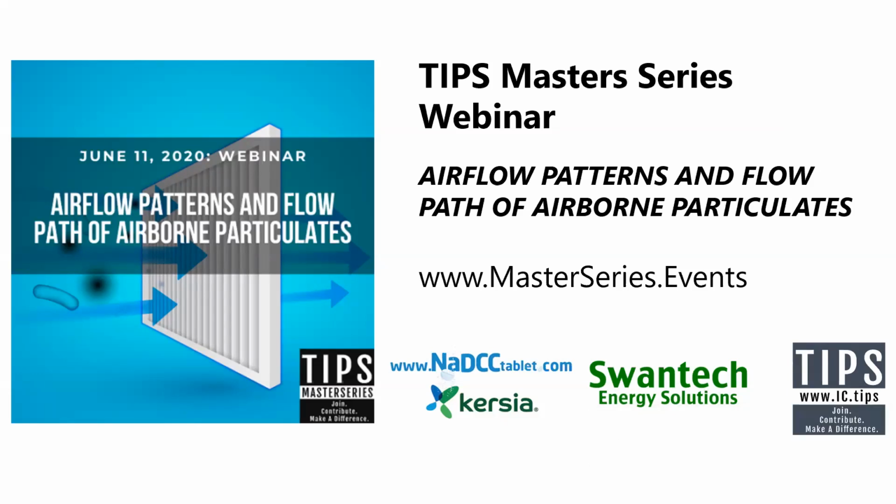Second step is to find out how you laid out your clinic, where your dental chair is, where your cabinets are, do you have any other major obstructions to airflow, and try to understand how air might be moving. The third step would be performing computational fluid dynamics analysis after you gather all this information. Understand how the air is moving. Once we know the analysis, once we see the airflow pattern, then we can decide what would be the right strategy to keep the space clean.